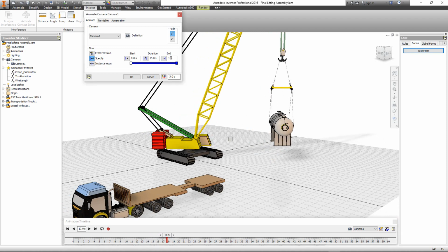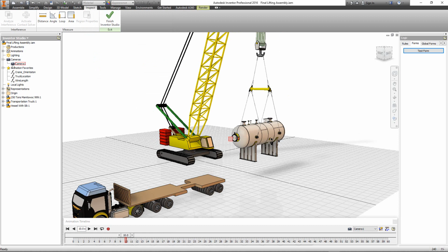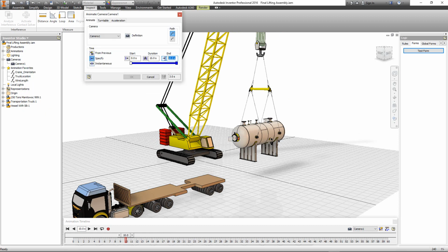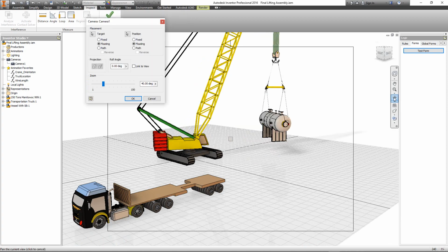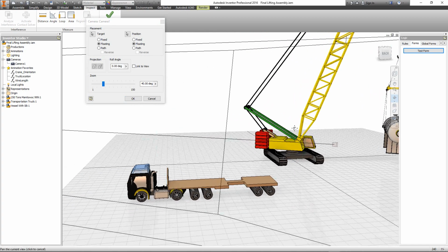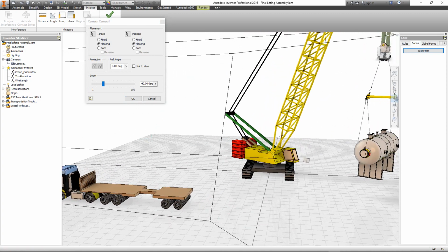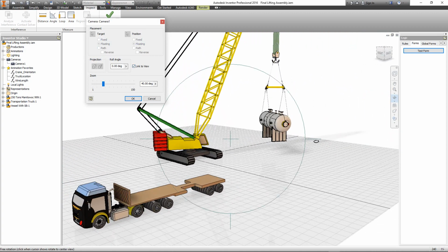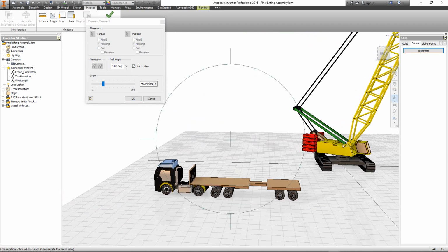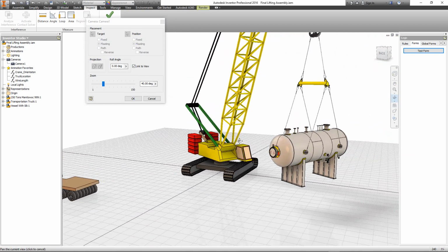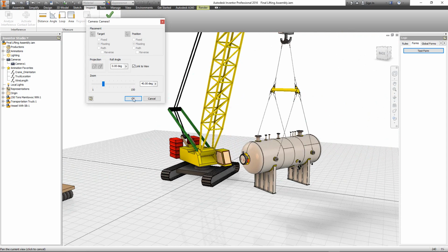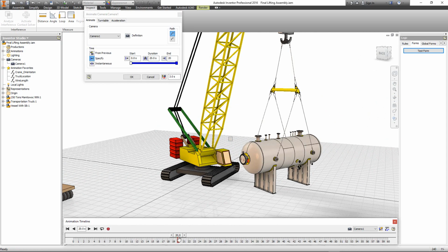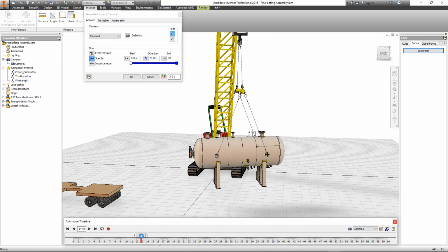By defining the location of this camera, let's click on it. Let's make it 10 seconds instead of 15, and click on OK. Now let's add another animation for this camera. It starts from 10 seconds. So let's start a new animation, and from specify, let's select 20, and from here let's link it to the link view. So select the link view first. After that, let's select the end view at the 20 seconds. So it's okay now. And let's test this.